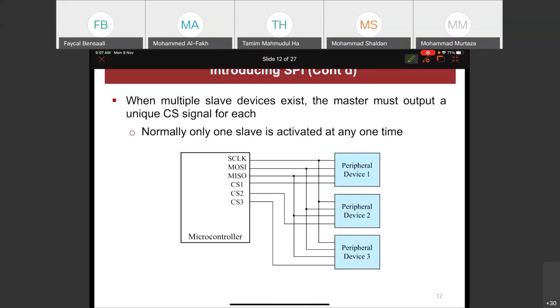So let's say that we have 3 devices, and each one transmits 4 bits. Do you see those 3 lines? The clock, master output serial in, and master in serial out. All devices can share those pins. And then we need a CS for each device to select. So we have 3 pins which are shared, and then we need 1 CS for each device.